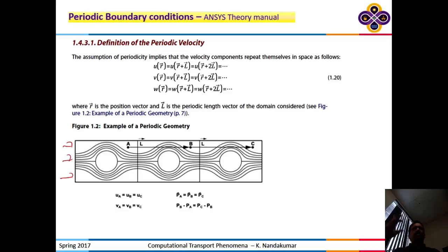This is the geometry. I have 3 cylinders, one behind the other, and I have an inlet boundary condition. You can build the geometry very easily in COMSOL and solve for that. Okay. A more clever way would be to say, I have a repeating pattern, so why can't I take a subunit of that? Because I can just translate that.